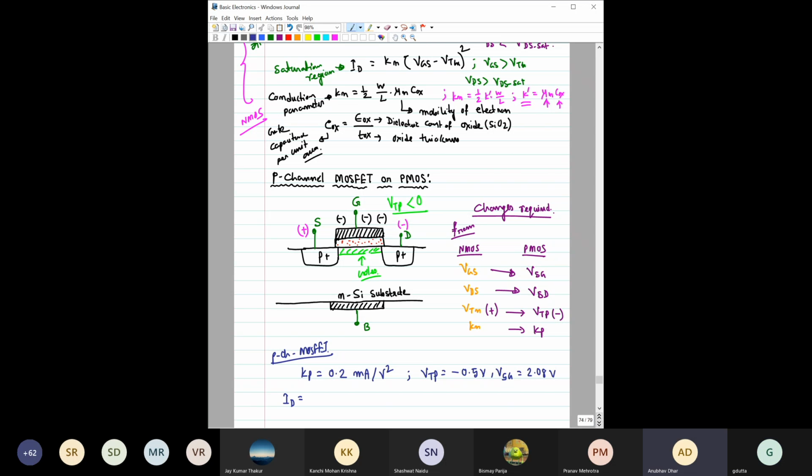Sir, I just applied the first condition. That first condition only tells whether the transistor is on or off. So whether the transistor is in saturation or in the triode region, we can't say because we do not have the full circuit here and sufficient information is not given. So let us mention that the transistor is operating in the saturation region.